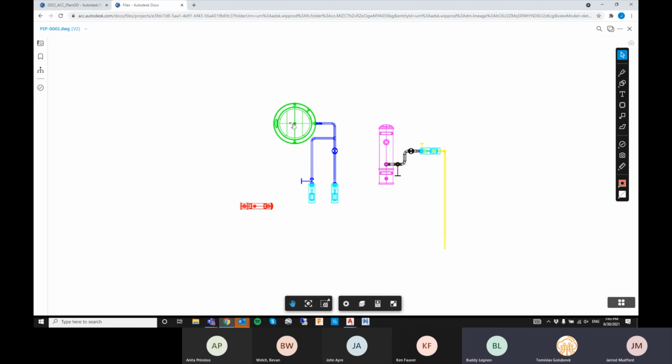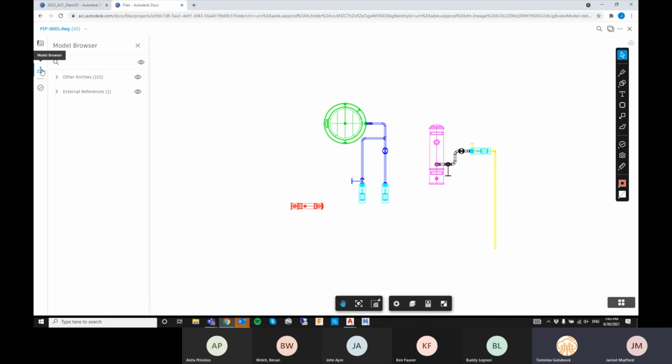So looking at it in docs, do you see your XREF? Yes. So click on the left. And here. Yeah, we are looking at it through docs. So there's the XREF there. Yeah. I just wanted you to know that if you leave your XREFs in your models, they will show up in docs. And so if you wanted to build out that master model that was full of XREFs, this is a great opportunity to exercise that.